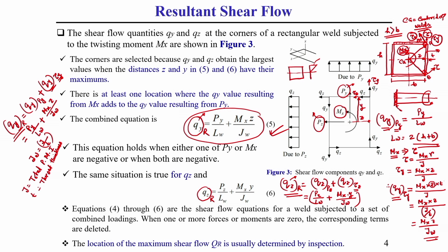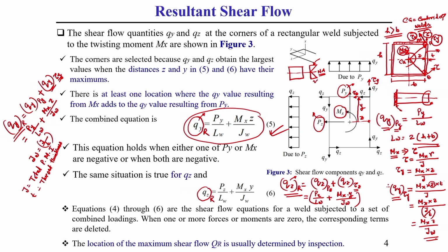It is maximum at the outer edge, and it is generally 0 at the centroidal axis, or you can say neutral axis. On the top side and bottom side, generally the same type of shear stress is distributed. What I am telling, understand. This you should keep in mind.